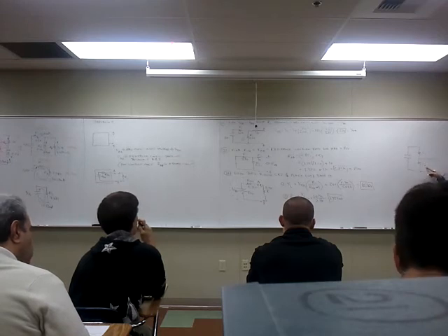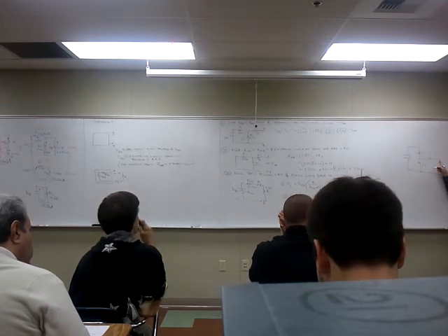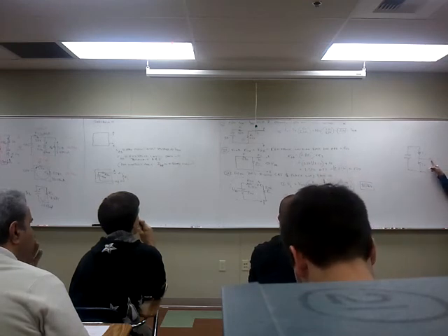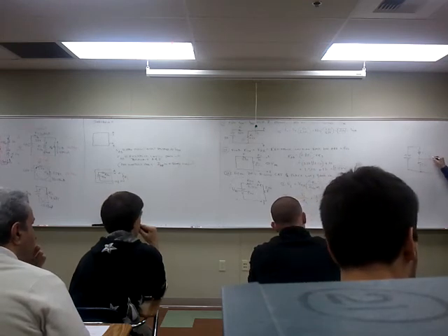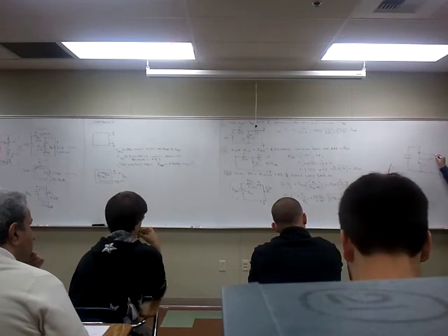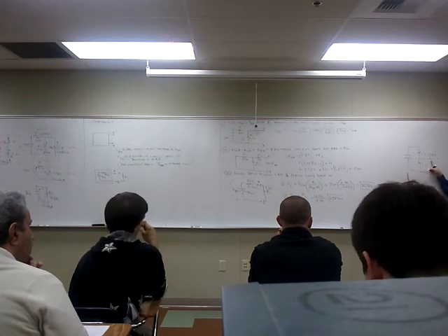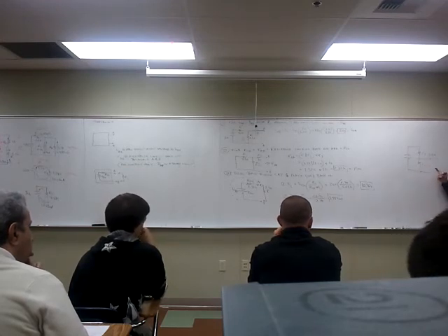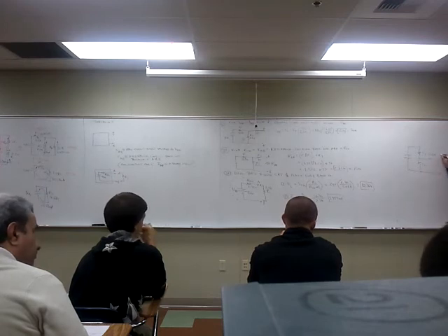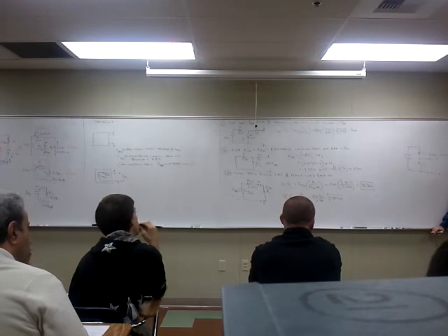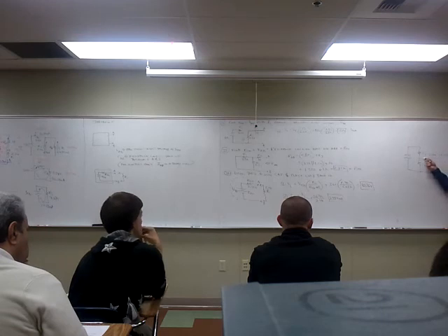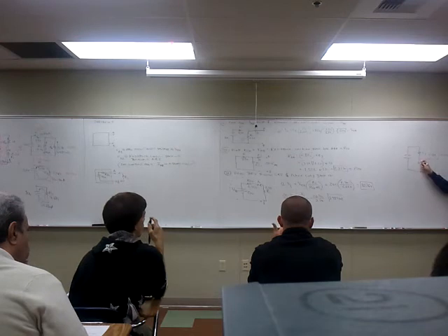How much of this V2 gets out to this point? Well, the voltage that develops across this resistor is equal to I times R. How much I is flowing through that resistor? 0, because there's no path. Since no current is flowing through there, 0 times any R is 0 volts, correct? What's the definition of voltage? Potential difference between 2 points. 0 volts means no difference between these 2 points, meaning whatever you measure here is identical to measuring there.